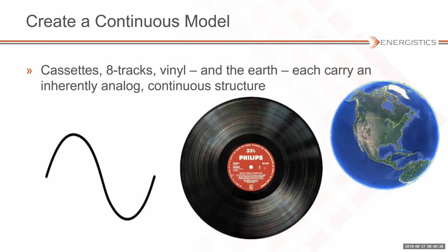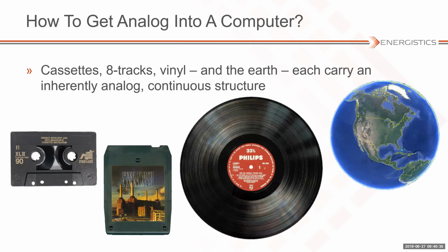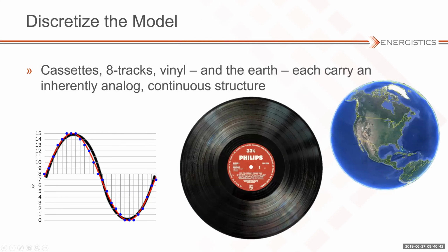So of course, the last step in getting sensor data is turning it into something digital. If we use a music example, tapes and vinyl are analog, which result in a continuous signal, but everyone knows that in fact we discretize this signal. We have a specific sample rate that we apply, and then the values that we calculate are digital values. They're not continuous. They must be either an 8 or a 9 or a 10 or an 11 in this particular example. So if I have an 8-bit analog to digital converter, it's going to have far fewer steps that I can associate the value with than if I have a 16 or a 32-bit analog to digital converter.